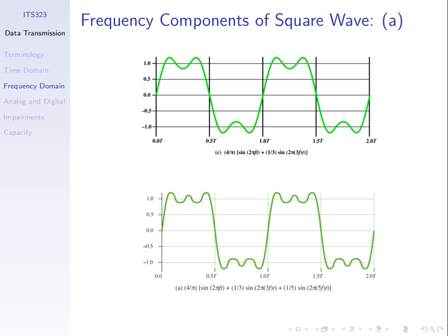And remember the data rate, we were assuming within one period we could send 2 bits. That is because every high signal represented 1 bit and every low signal another bit. So in one period we have a high and a low, therefore 2 bits in that case. We know the frequency of our signal.